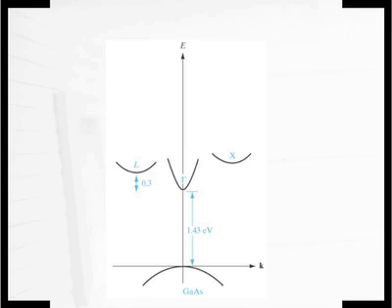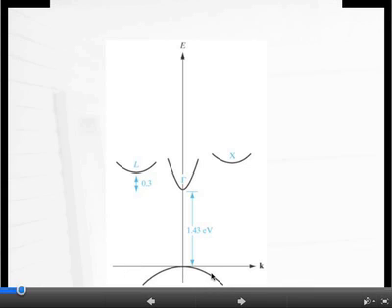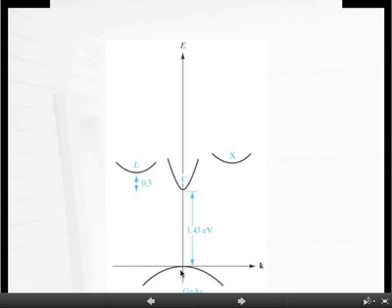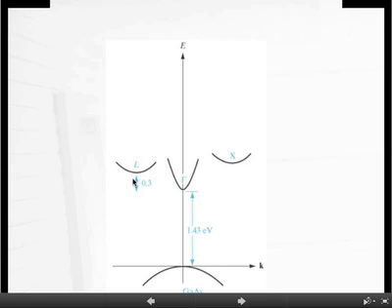So this is gallium arsenide, okay, what we saw before. But now we have also added a couple of other bands on the sides, okay. So we have a couple of terminology I need to point out. First is that this point here of the crystal direction, when k equals 0, in gallium arsenide is referred to as capital gamma. It's hard to see for you guys, but that's what that is. Okay. The next higher band, whose k vector right here, is referred to as L.